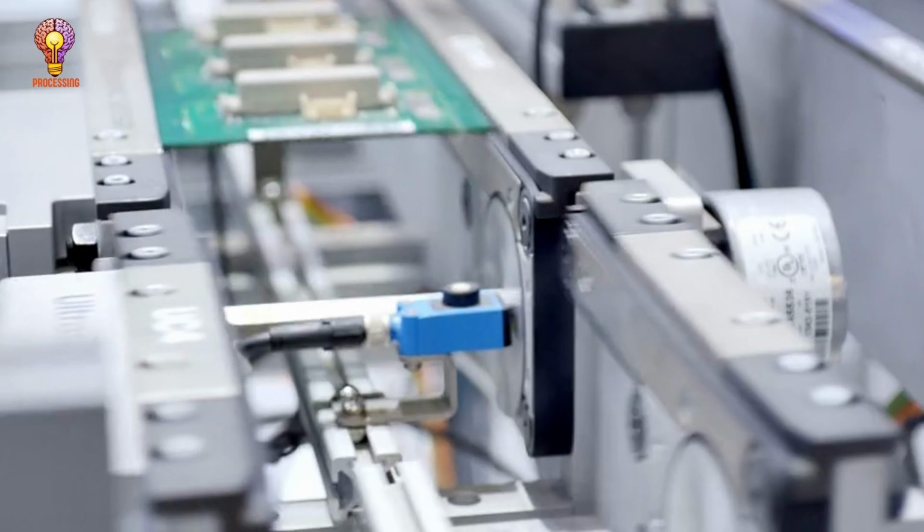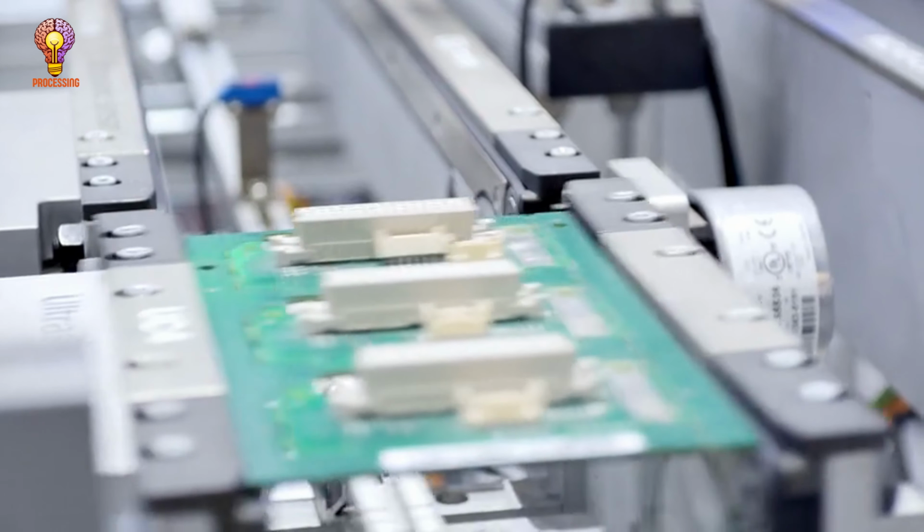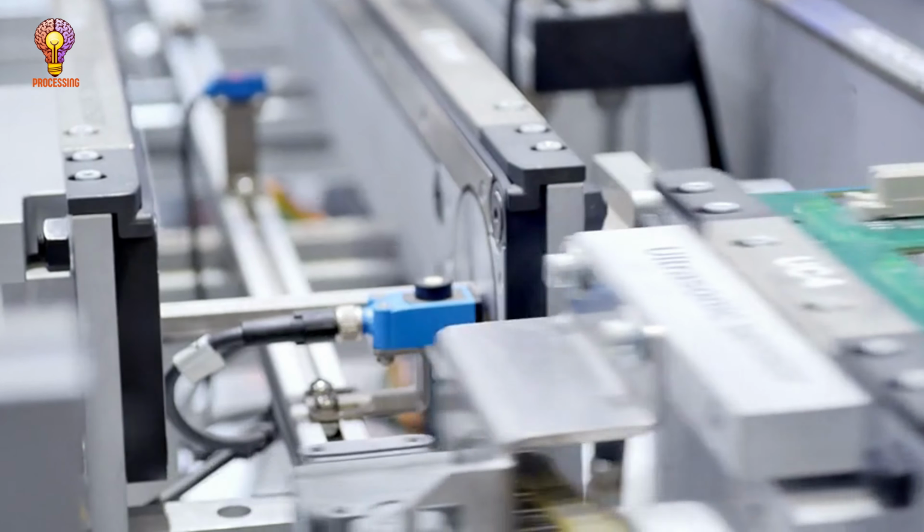3. Computer assembly and automation. Once all components are manufactured, they are assembled into complete systems using a mix of human labor and robotic automation. A. CPU and GPU installation. The processor is placed into the LGA (land grid array) or PGA (pin grid array) socket. Thermal paste is applied, and a heat sink or liquid cooling solution is mounted.